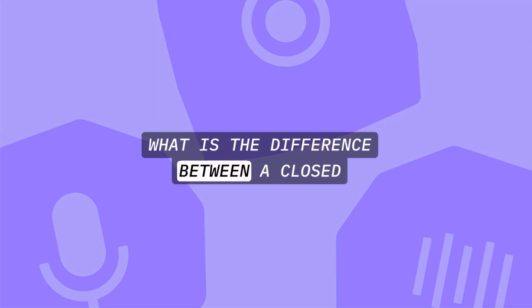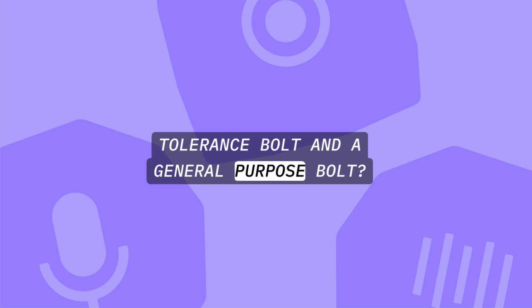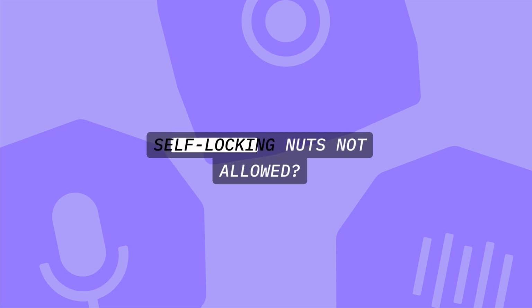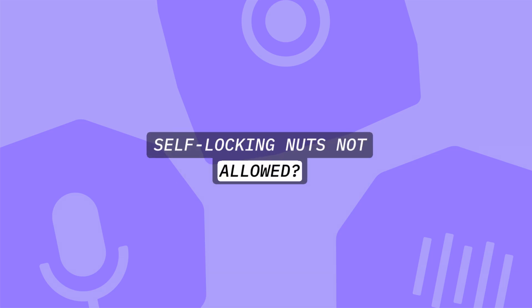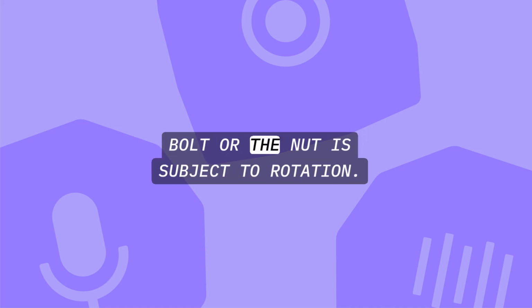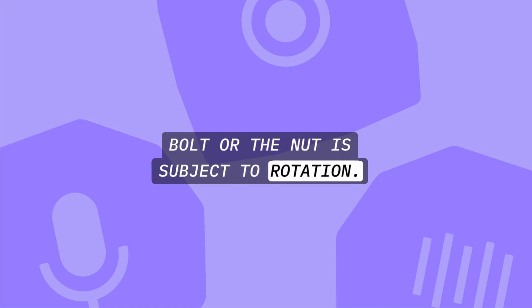What is the difference between a close tolerance bolt and a general purpose bolt? Close tolerance bolts are machined to more accurate dimensions. For what types of application are self-locking nuts not allowed? Self-locking nuts may not be used when either the bolt or the nut is subject to rotation.